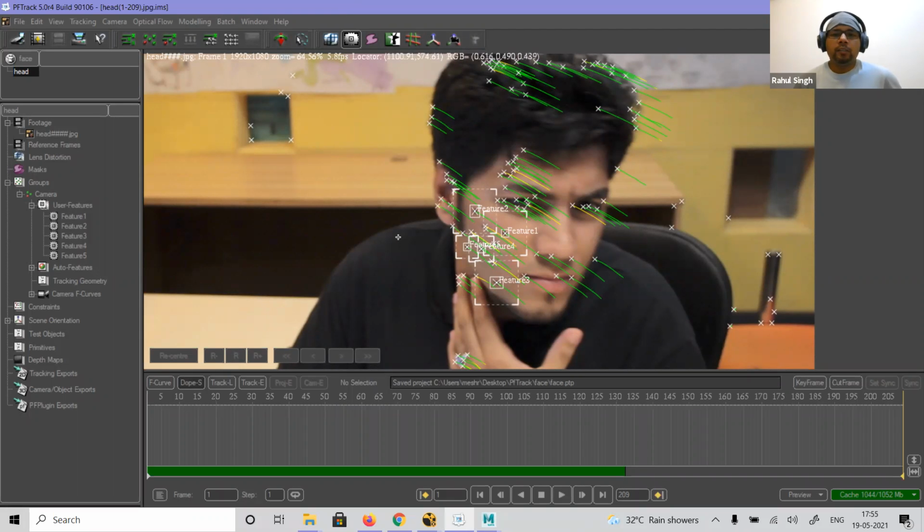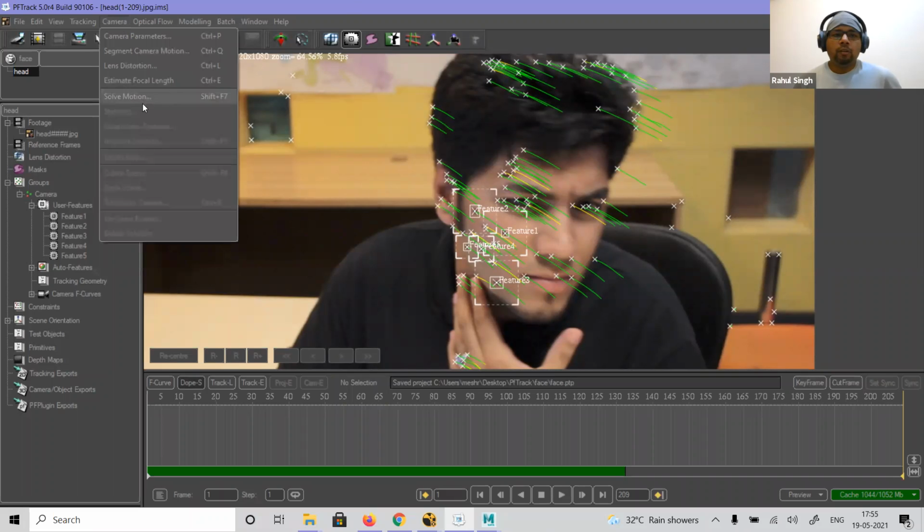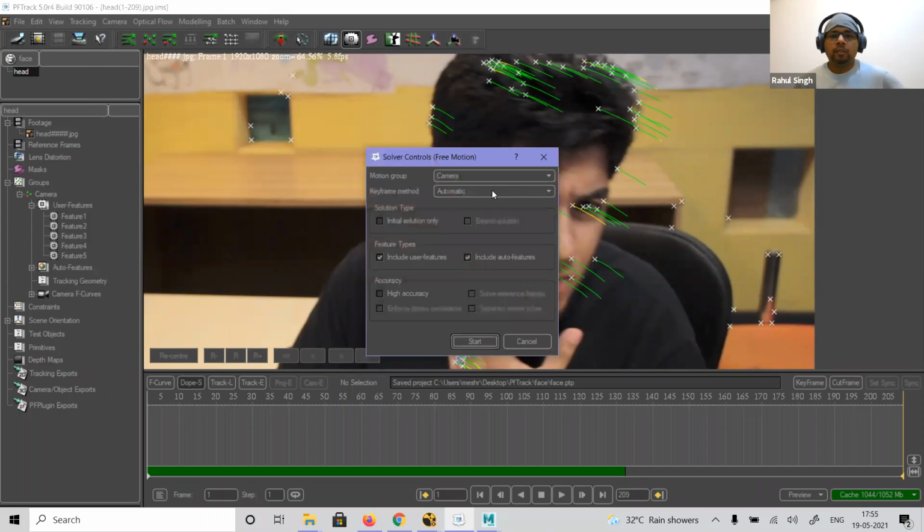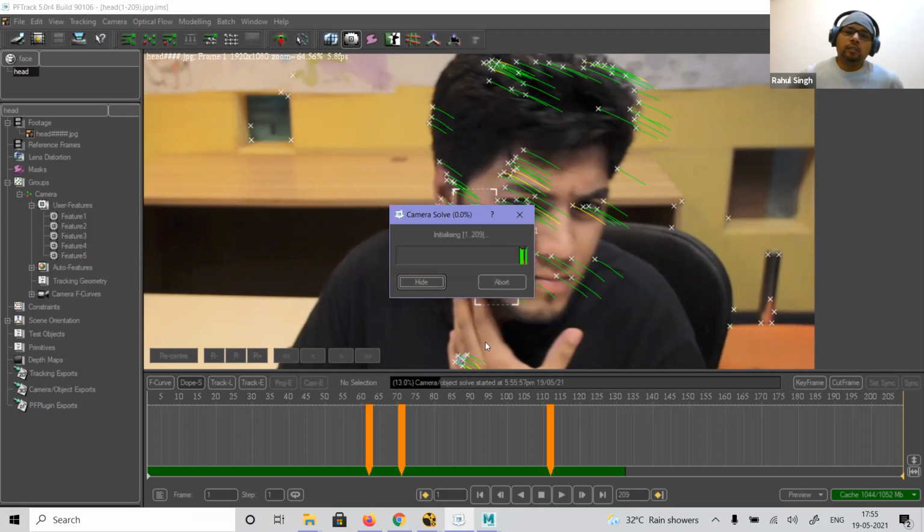Okay, we got this information, right? Now let's solve the camera. Keyframe method automatic, include user feature, auto feature both. Yes, fine. Start. Let's try to solve the camera.